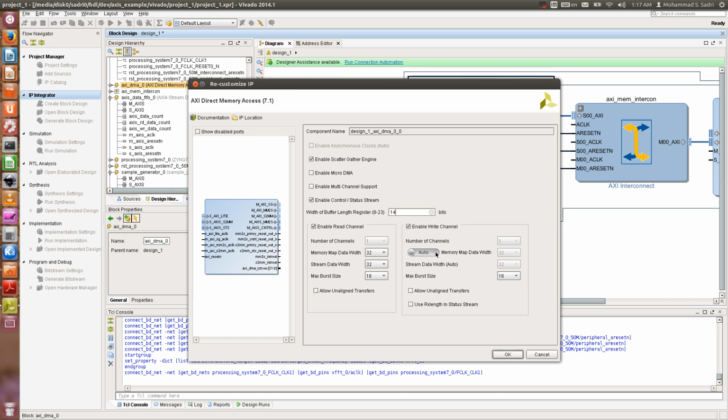Indeed, if I disable this mode, what happens is that every time the DMA engine performs one data transfer task, it should interrupt the CPU, and the CPU should reprogram the DMA engine for the next transfer task.